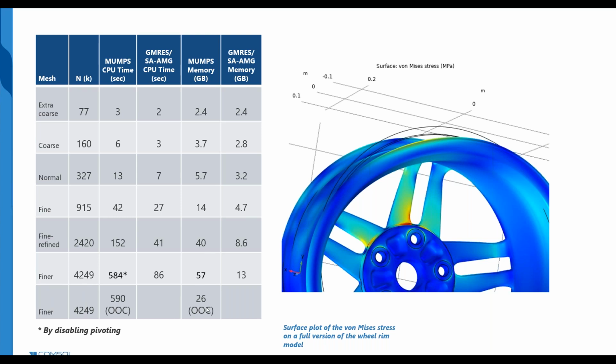But not without effort. So the out-of-core option kicked in automatically, and that worked pretty well. Here, it did not kick in automatically. I think I had to enable it manually, and that works well here. But without doing that, I got an out of memory.